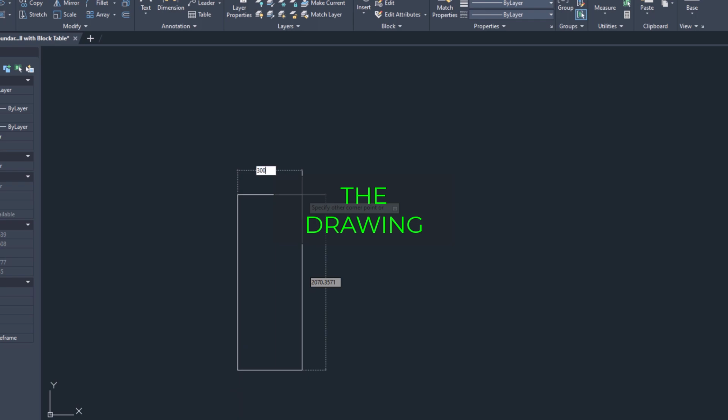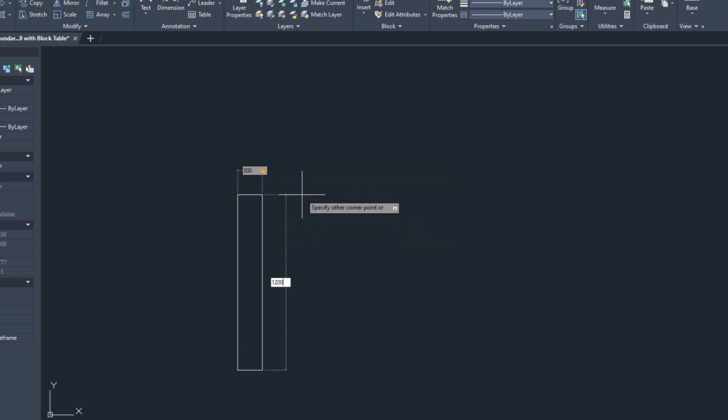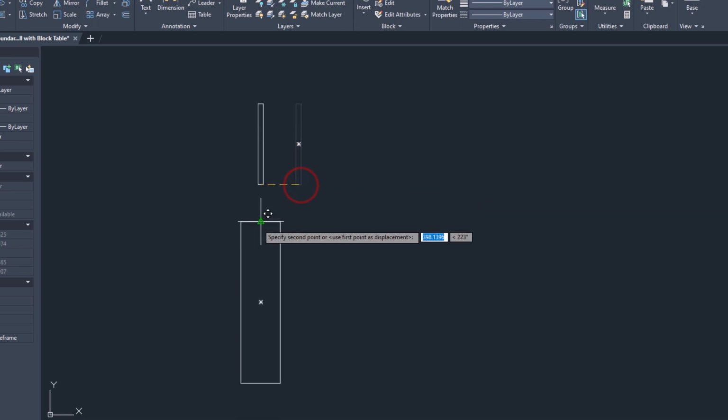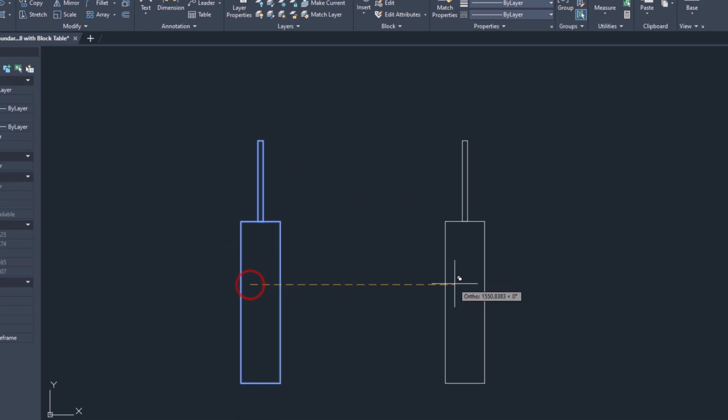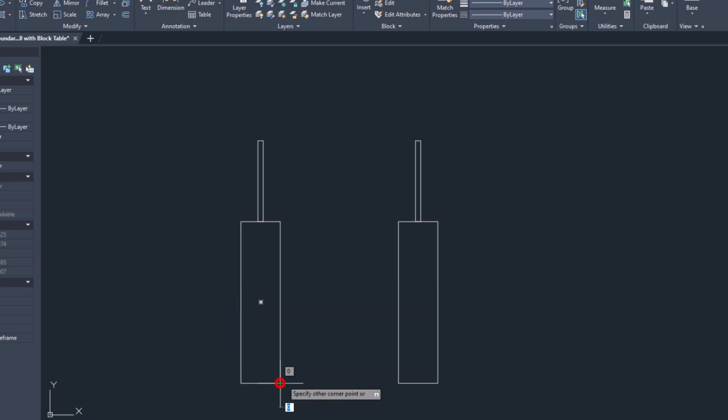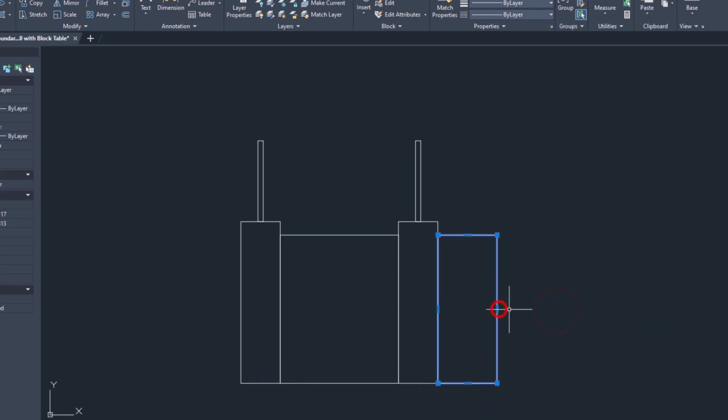First, I make an elevation. The post should be 300 wide and 1200 high. The fence post width should be 40 and the height 600. Copy the post to 1200 millimeters. Draw 1100 high wall between the two posts. Draw half-wide walls on the other side of the posts.